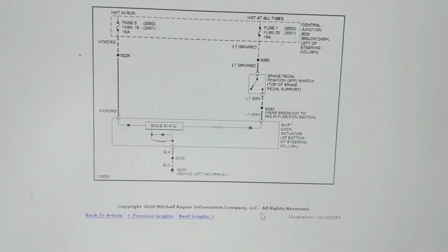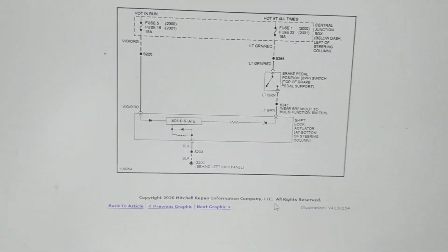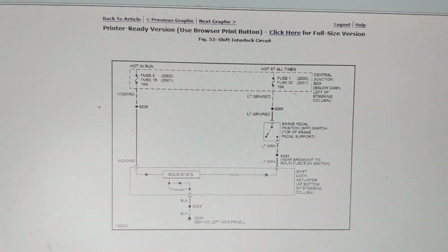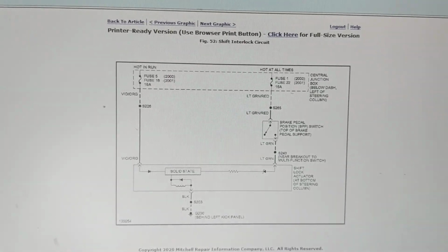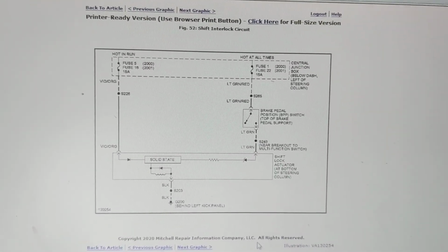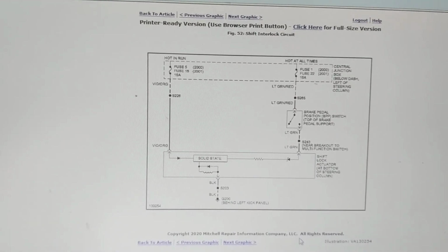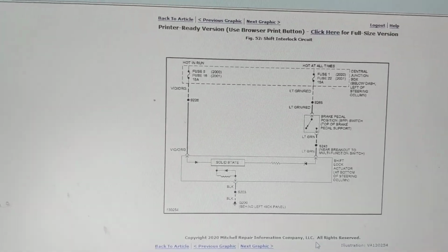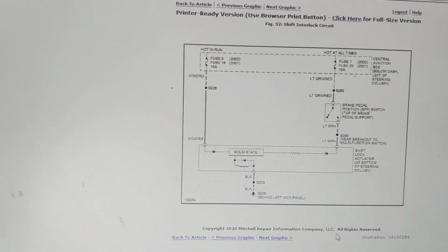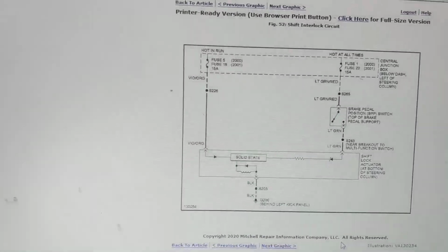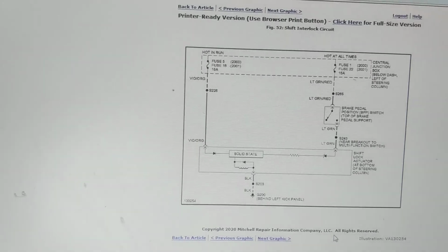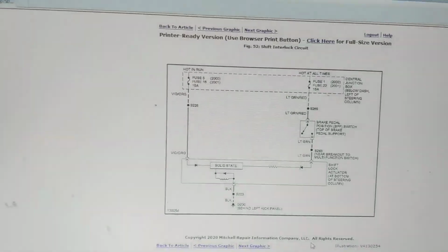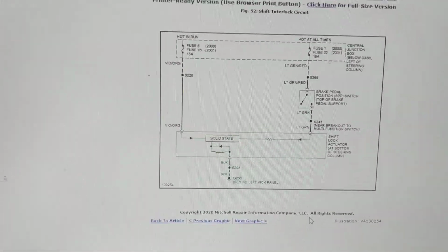And I just wanted to mention the clamp meter. Just because there are videos out there about the best clamp meters doesn't mean that it's necessarily appropriate for automotive. Like I said before, those have very large jaws and the meter itself is very large. You have to get into very cramped locations when it comes to automotive. And that's why I use the small one. It fits, as you saw when I measured the alternator current. So don't be attracted when they say the best meters. Remember, those might be for electrical, where wires are easy to get to. Wires are not easy to get to in automotive, not at all. So you need a small one.